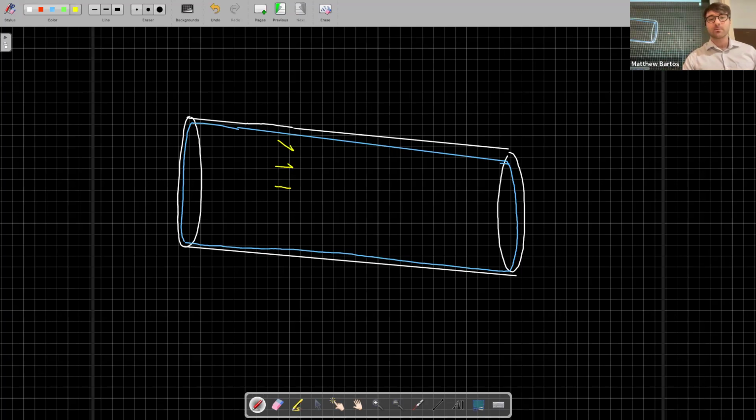For our case, we're interested mostly in the forces acting in the direction of flow, because we're interested in how the momentum of the fluid changes with respect to the direction of flow. So what force in the direction of flow would the normal force give rise to? Friction, right? So there will be a frictional force exerted by the pipe wall.